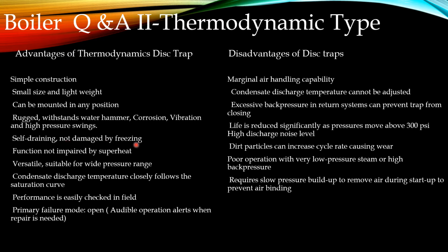Self-draining, not damaged by freezing. It is self-draining and also it will not be damaged due to freezing or low temperature. Function not impaired by superheat. Superheat temperature steam also can be handled. It will not affect the trap. Versatile, suitable for wide pressure range. Various ranges of pressure it can be used.